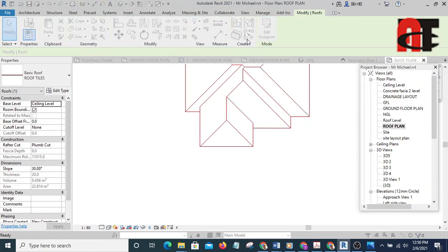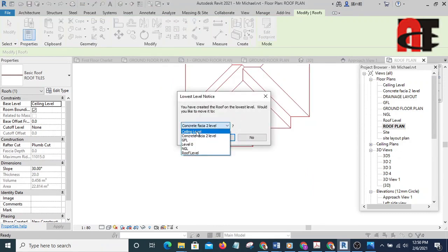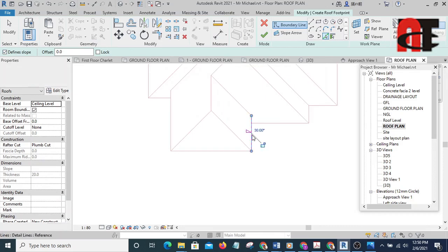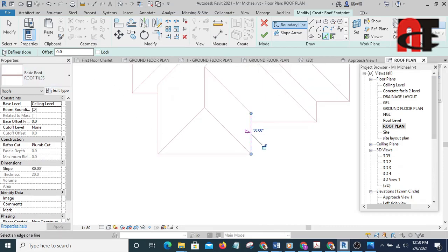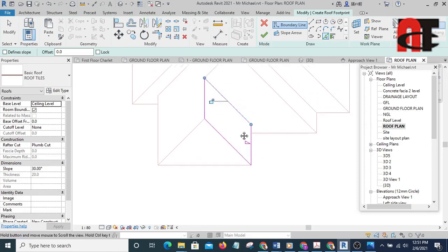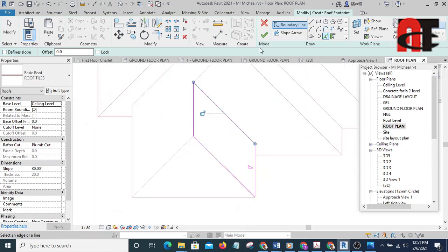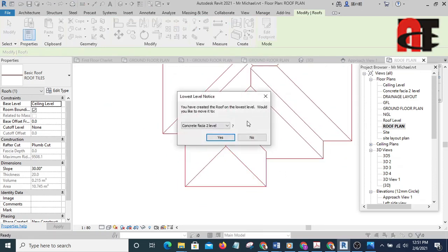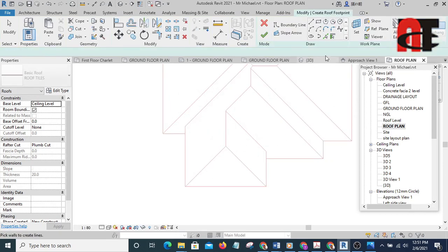Alright, then I'm going to create similar. Select the same level. Then I'm going to pick line. The first one here will be defined. Then these are not going to be sloping. So I'll hit save. I'll create similar again. Select my level and I'll pick line.